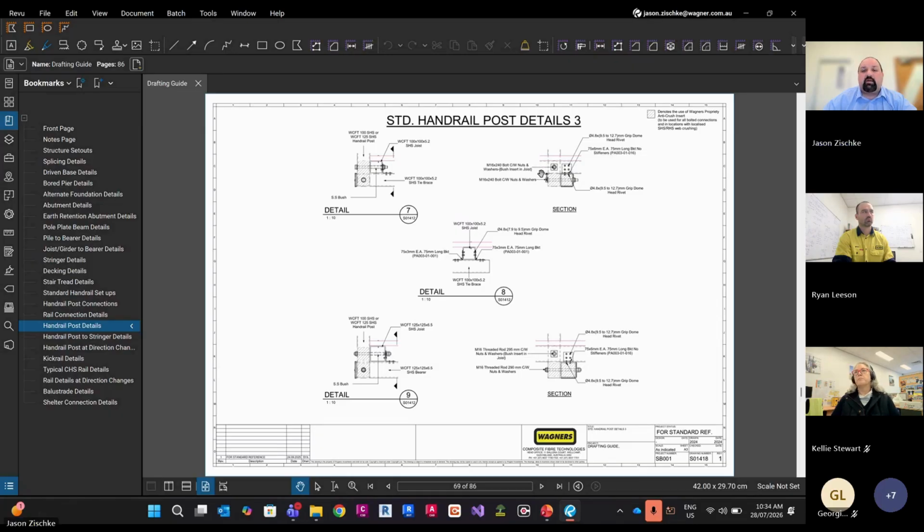Over time, talking with contractors and understanding their constructability concerns with this connection, we went into development and modified it. First, we took away the inserts and started using bushes in the joists. We still use inserts in our posts and the tie brace, because those we generally manufacture here.